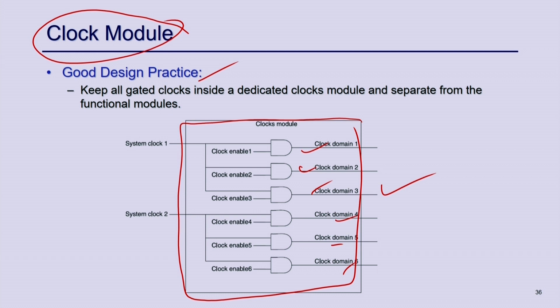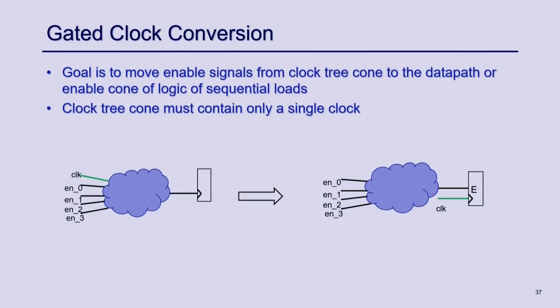So, this is a good design practice that you should follow when you are thinking about ASIC prototyping of your design, FPGA prototyping of your design, right. The second thing that the FPGA synthesis tool does is gated clock conversion. It does the reverse of gated clock.